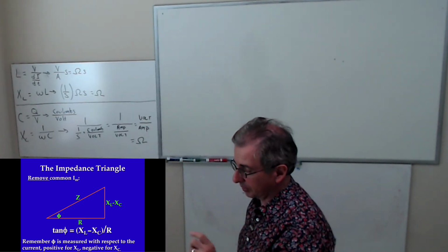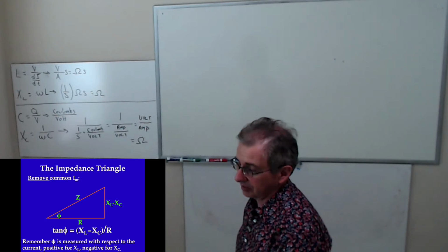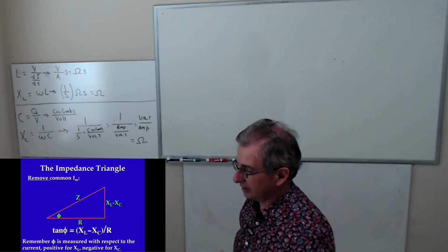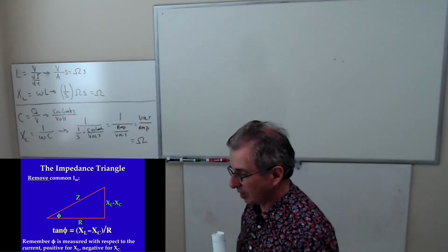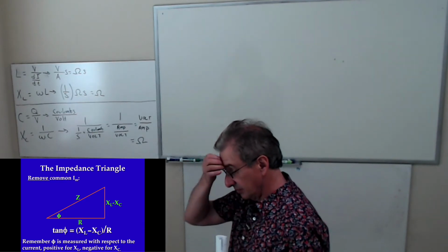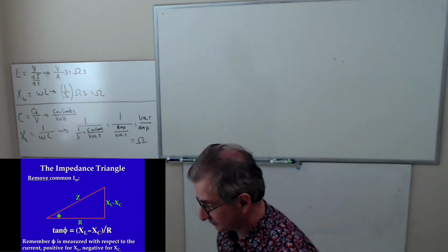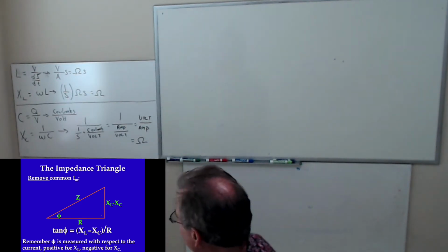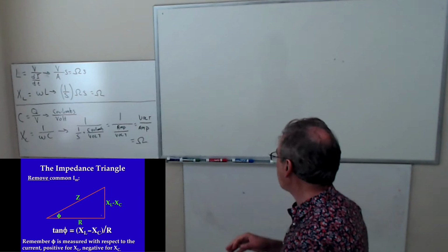Okay? I mean, on the scope, it's going to be 1 volt peak to peak, but on the multimeter, it's going to be about 0.35 volts, that ballpark. Okay? But you should record that. Okay? All right. So based on that, I'm assuming everybody can hear me.